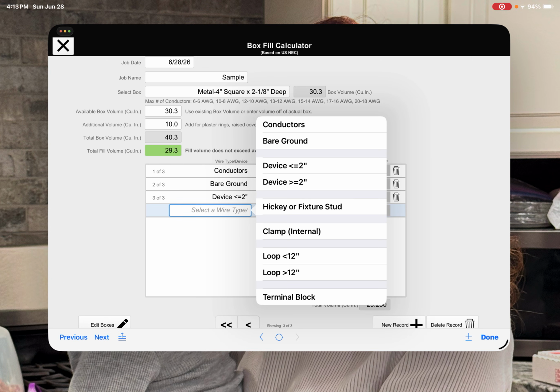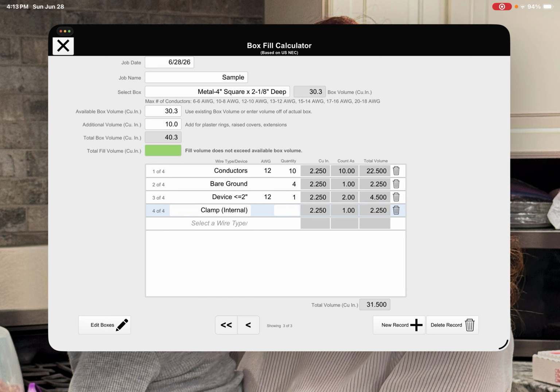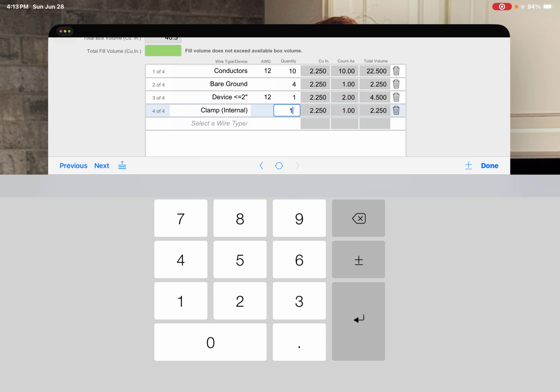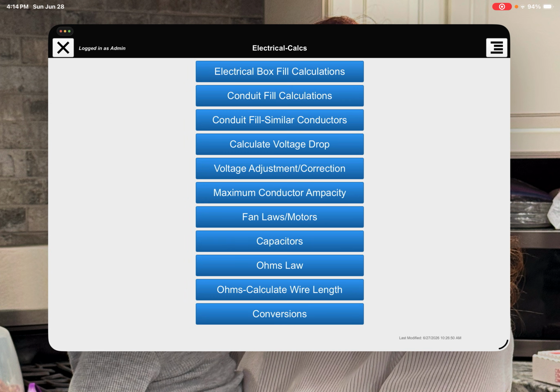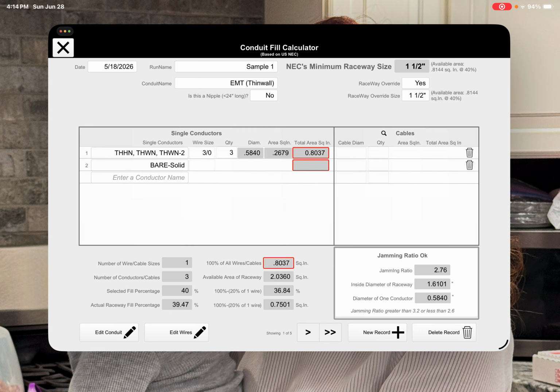And what else? Internal clamp. We'll throw an internal clamp in there. And it'll do all your calculations. You've got 31.5 in the box. You see that in green. And it's green because it doesn't exceed the box volume. And that's simply it for box fill calculations. Same thing with conduit. Conduit's a little more involved. Starting from the top, you'll see...